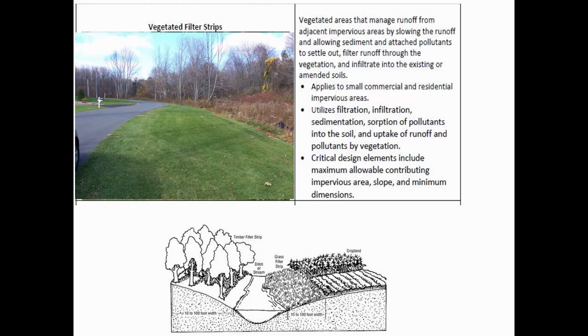When you've got a depth of water, it can move with less resistance through that channel than if it's flowing as a sheet. So you just think, what kinds of flows are slow? Sheet flow. What's going to improve infiltration? Vegetation. And so that's the idea of a filter strip. And this is showing it next to a roadway. There are places where they do the same thing in a parking lot, where just putting in patches of grass in a spot where you know peak cars aren't going to be parking can have an enormously positive impact. And also it improves the water quality as well.